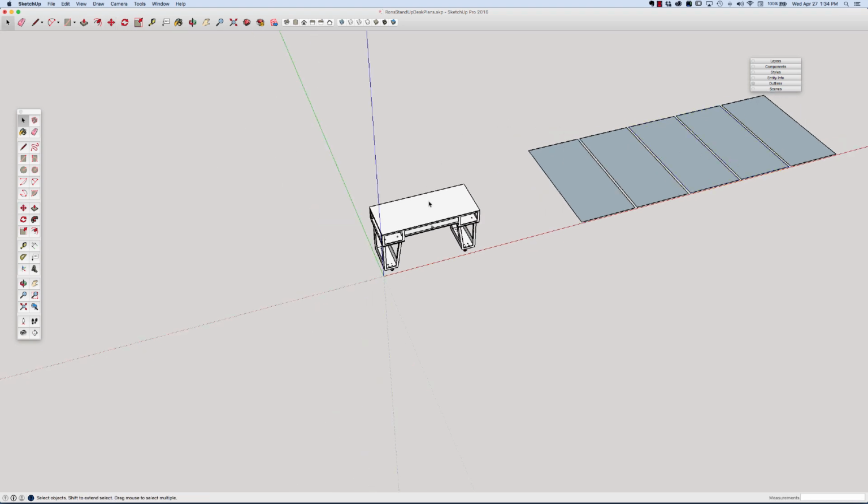And now what I'll do is take the whole model, and I'll hit the M key for move, tap the Alt key for copy, and I'm just going to drag a copy over here. And what this copy is for is, I'm going to right click on it, or left click, and I'm going to explode it. And that explodes it into its 3 basic groups. And then I'm going to grab the top, hit move. And my goal here is that when I'm all done, there'll be no parts left here. And that way I'll assure I get all my parts laid out.